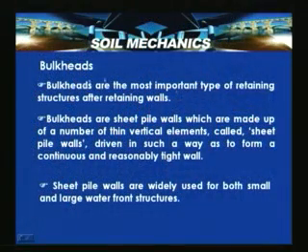So bulkheads are the most important type of retaining structures after retaining walls, and these are used in waterfront applications. Bulkheads are sheet pile walls made up of a number of thin vertical elements. Standard sheet pile sections are available, and these are driven into the ground and connected in such a way that they form a continuous wall.